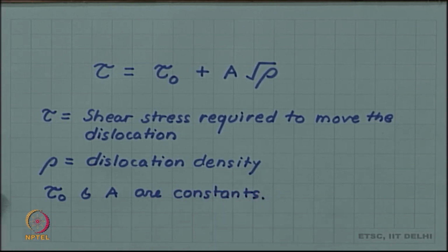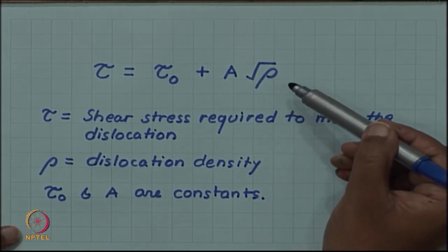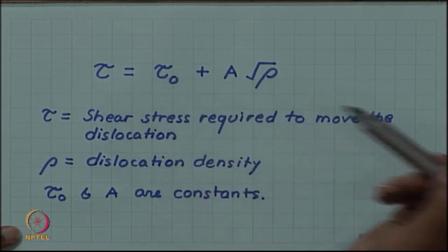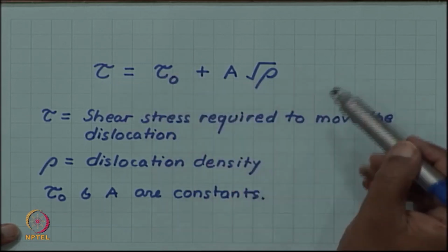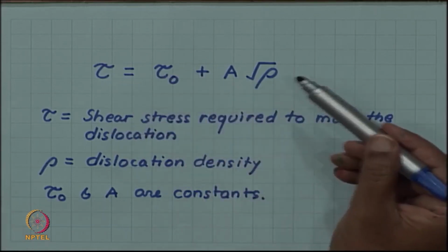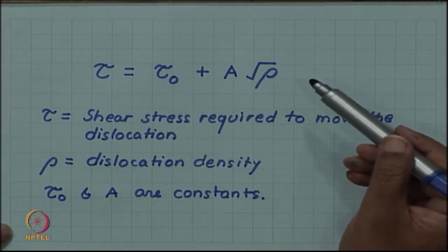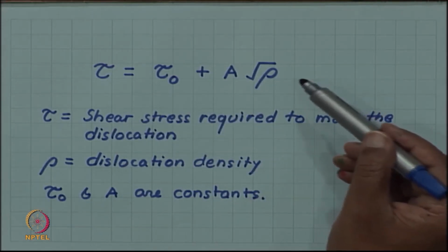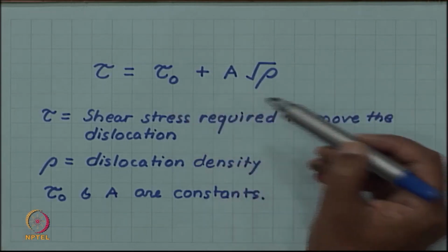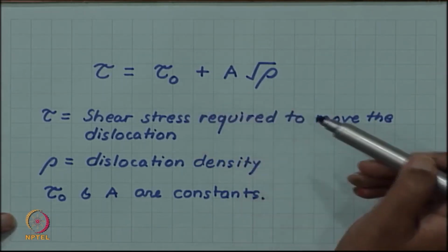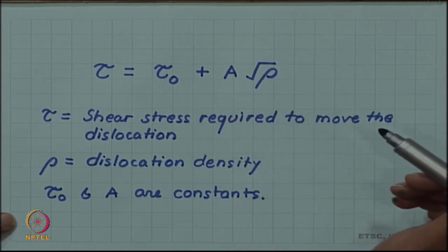So, you can see as the dislocation density increases, the stress required to move the dislocation will also increase. We are not deriving this relationship; a simple derivation is sometimes possible in terms of a simple model of dislocations, but we will not go into that, and empirically also such correlation can sometimes be established.